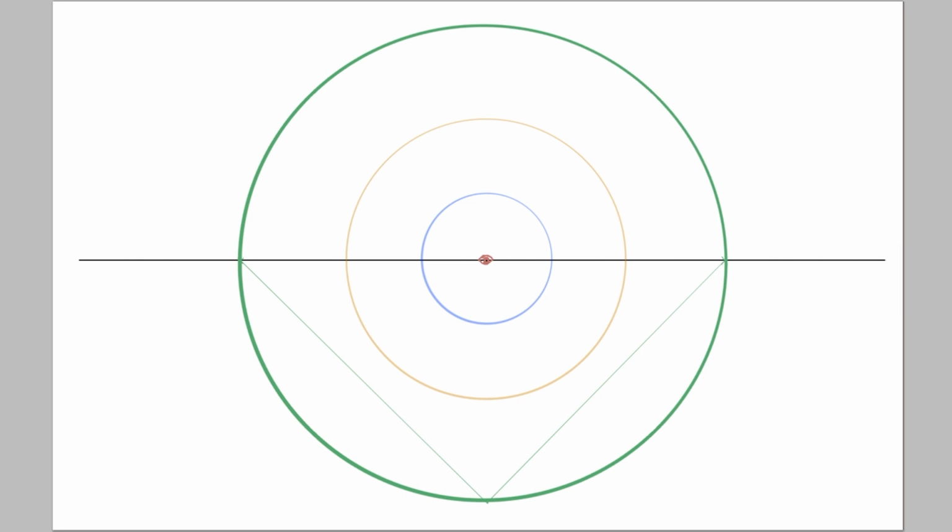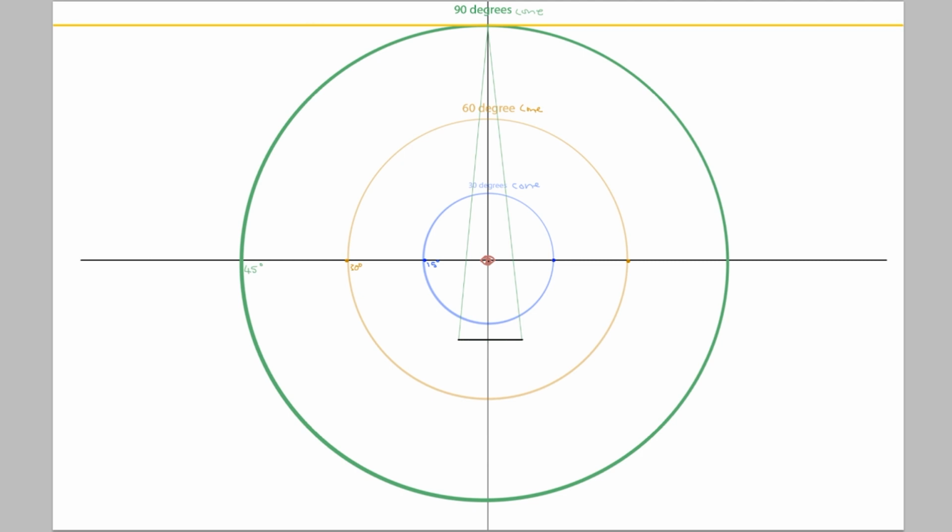However, since the cube is now going to be tilting up and away from us, we need to talk a little bit about what happens when parallel lines tilt vertically up, like so. These parallel lines are going 45 degrees upwards, and as such are going to line up on this vertical axis coming out of the center of vision. This creates what we're going to call a false horizon, and any degree of turn from these parallel lines to the left or right will disappear to a point along this false horizon, as opposed to the true horizon. Any lines tilted up 45 degrees will lie somewhere on this false horizon.